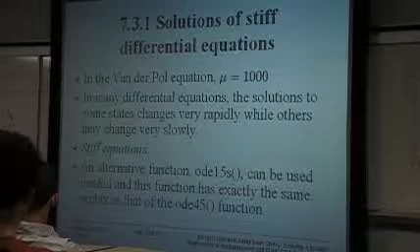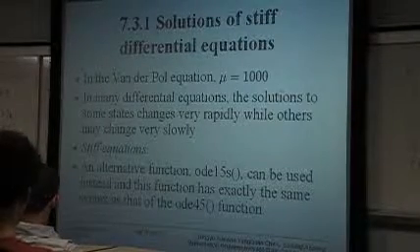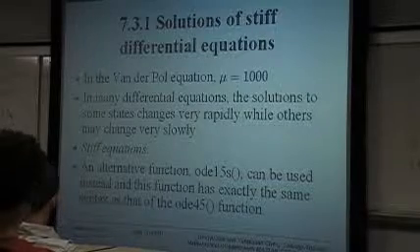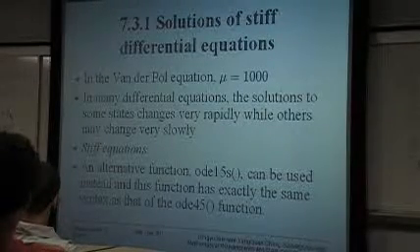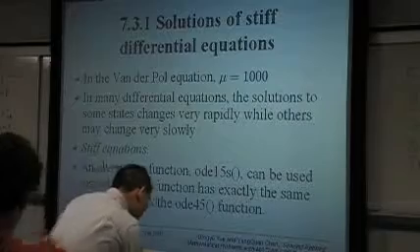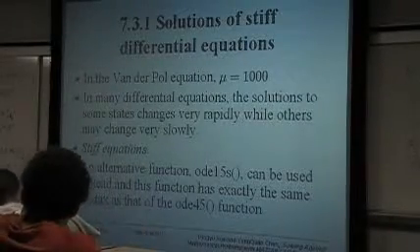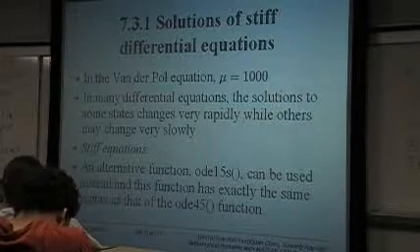And if the step size is selected too small, then the total number of calculation points will be huge. So this causes a not enough memory error. No matter what the memory of your computer is, you may have that kind of problem.